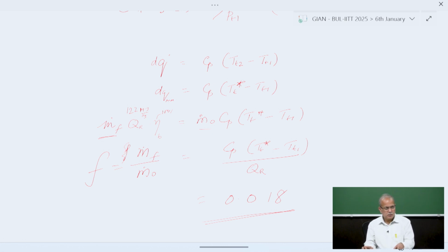Okay, all of you have finished this one? So you got the grasp about what we did today. This morning we went through the overview of the gas turbine powered engines. We looked at the turbojet engine, and the turbojet with an afterburner, and their corresponding cycle diagrams. Afterburner is used for thrust augmentation. You use it only when it is required because it is related with the penalty of fuel consumption.